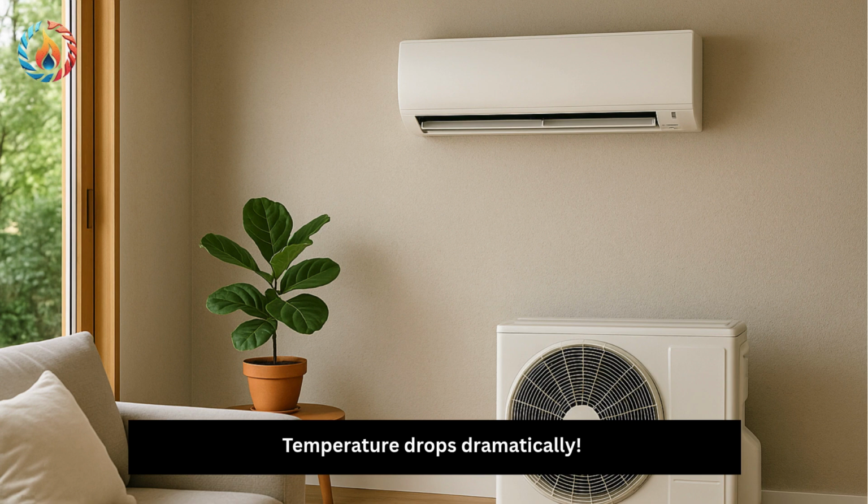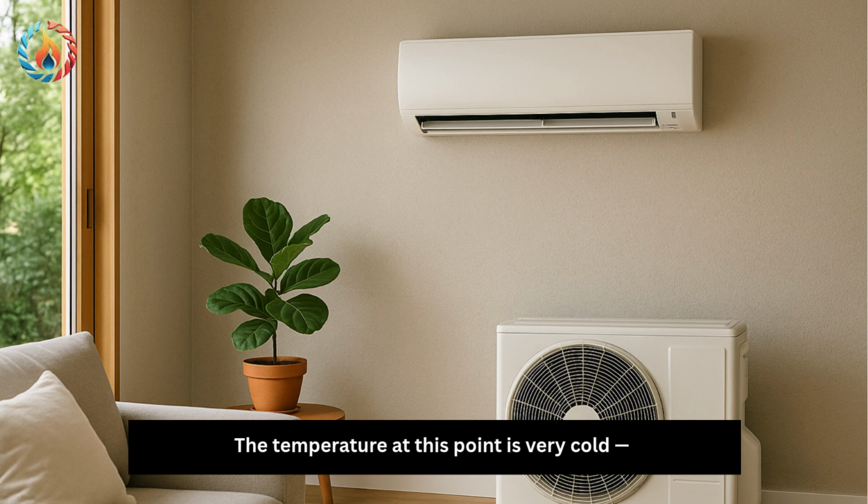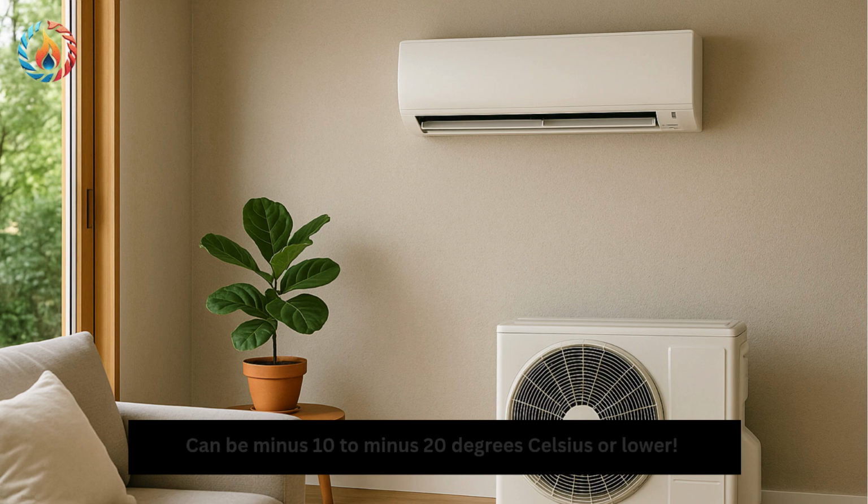Temperature drops dramatically. The refrigerant exits the expansion valve as a low-pressure, low-temperature mixture of liquid and vapor. This is called a two-phase mixture or wet vapor. The temperature at this point is very cold, can be -10 to -20 degrees Celsius or lower.